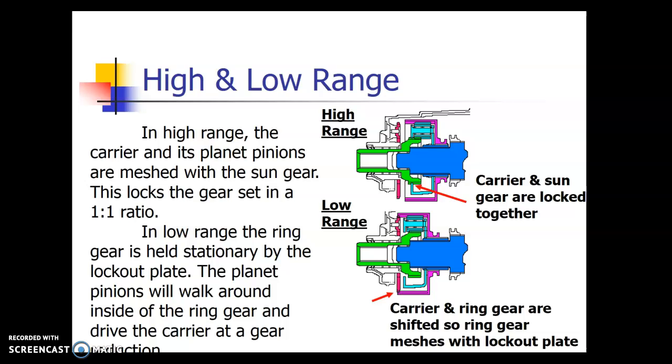So overview, real quick. I know this gets more complicated than this, which you'll learn more about in our transmission drivetrain class. But overview here is this: transfer cases are going to redirect power from the rear to the front when you need it, when you shift it into four-wheel drive. It can also, in a part-time four-wheel drive, do high and low range. Again, there's going to be gear reduction. So you shift it into low, shift it into four-wheel drive. This transfer case unit is going to send power rear and front, and it's going to change the output to a low range or a high range.